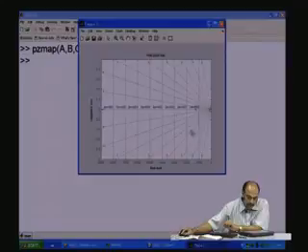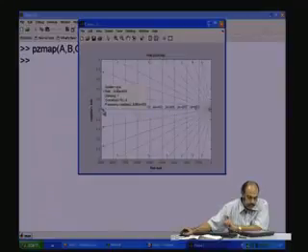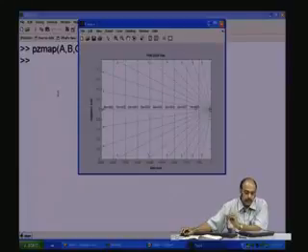So, you see there is one pole here at the frequency of minus 1240 at this point. Damping is 1, you see it is on the real axis because there are no overshoots. And then there is another pole here at a frequency of around 8860, again damping is 1, no overshoots. Now, let us freeze this and see what happens. You see there are only just two poles.